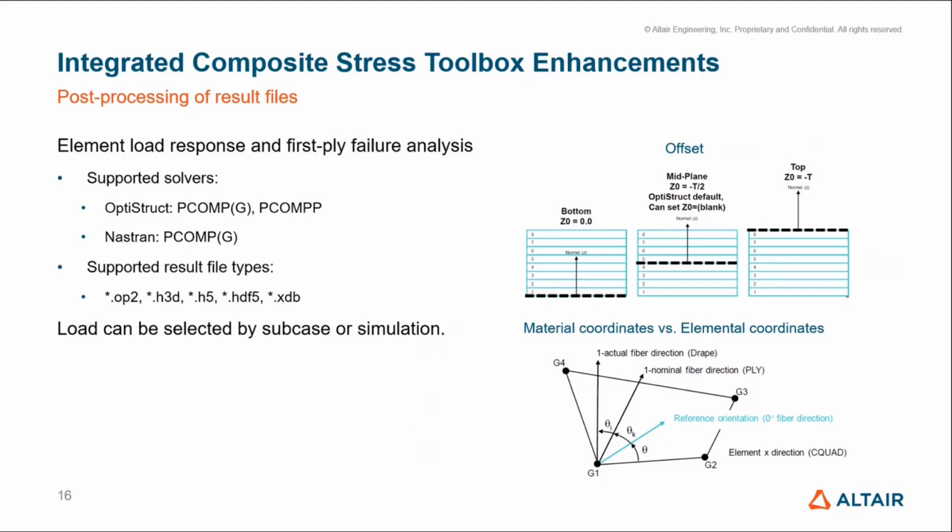Just in here, we can immediately go to the various elements and to the full thickness plots for the stresses and reserve factors. Again, here important to note that we do everything with the correct offset and also the correct relation between the elemental coordinates in which we read the forces and the material coordinates.